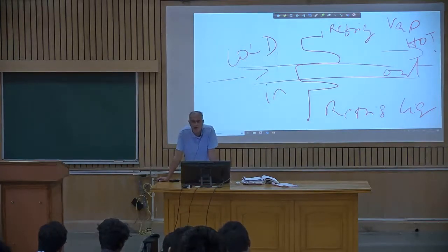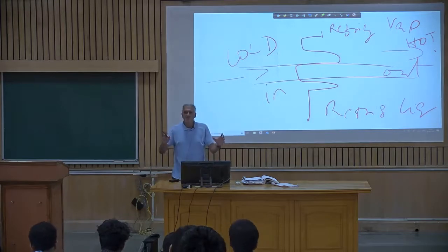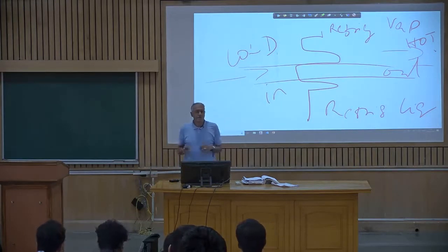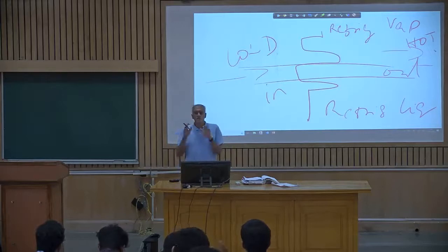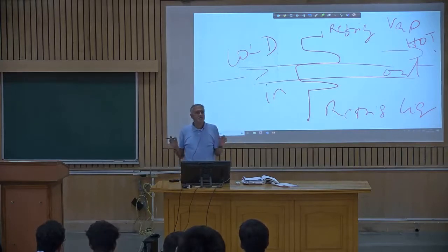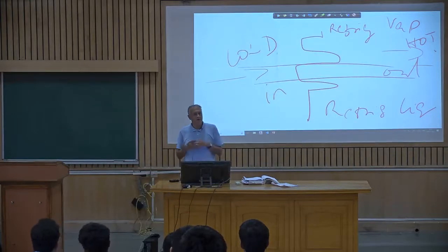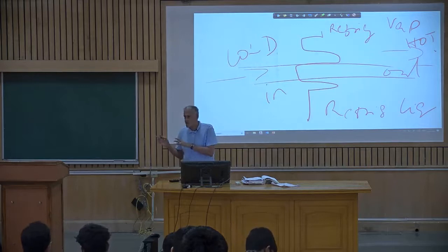Okay, now you do this one exercise. I think this will take care of your chapter. So what did I break up your entire equation into? Heat giving in, heat taking out. Work giving in, work taken out. Flow enthalpies, macroscopic potential, macroscopic kinetic.